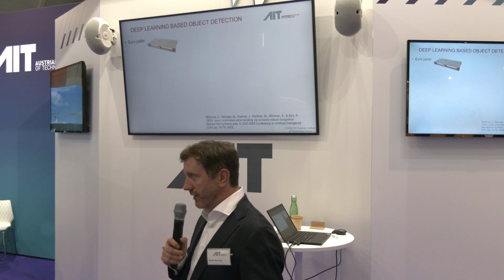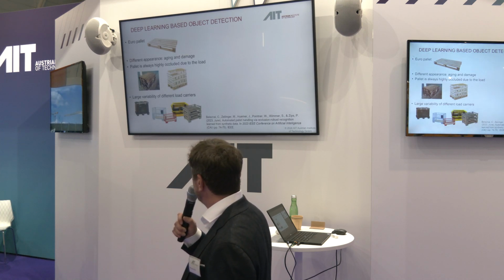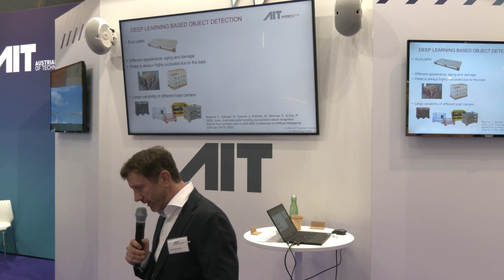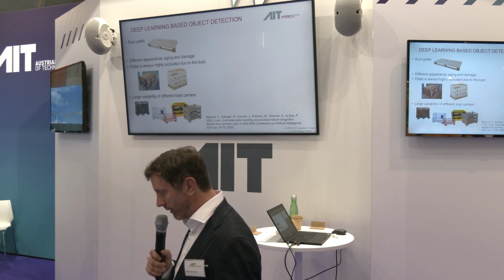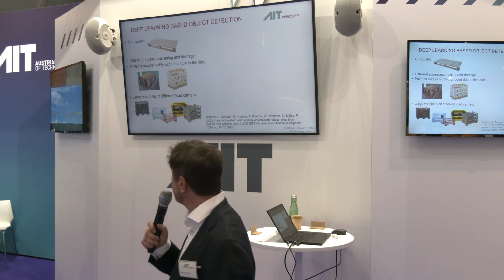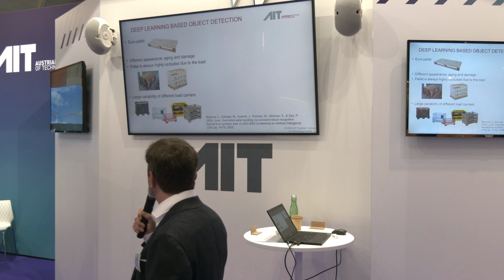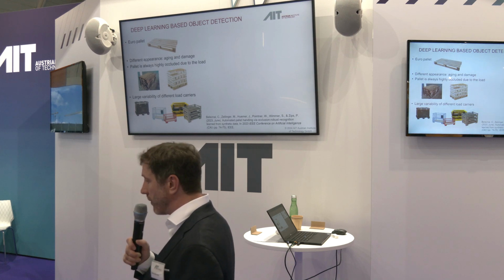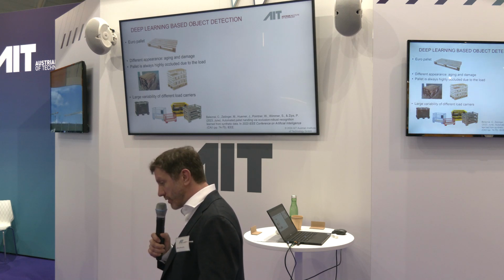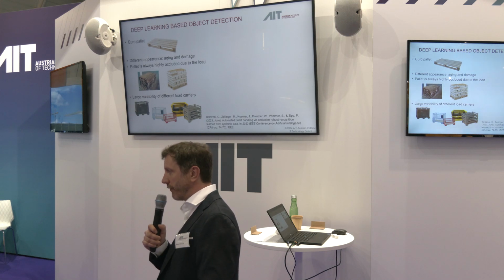Okay, now the pallet detection. Obviously, if we want to move pallets, we have to detect them. Usually we think of Euro pallets for now. What is the difficulty here? That they look very different at different age, but also in different weather conditions, if they are wet or if they are old, and all these things have a huge impact on the appearance, which made us think that we should go the direction of using geometric features as a main anchor for the detection, and